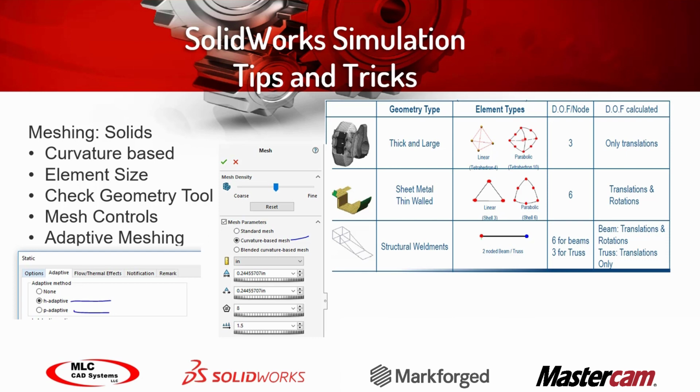So if you think of a beam and I'm putting down a load in the middle of that beam that's fixed at both ends, in a solid environment I need many more elements in there, or calculation points, to look at and analyze that bending in the middle of the beam. Whereas if I use weldments to model my CAD geometry and I use beam elements in my simulation study, those elements would be allowed to rotate, so I don't quite need as many. So I get the same results. The solve time is better if you use the shell or beam elements, and of course there's a couple applications where that would apply that we discussed in the training as well.